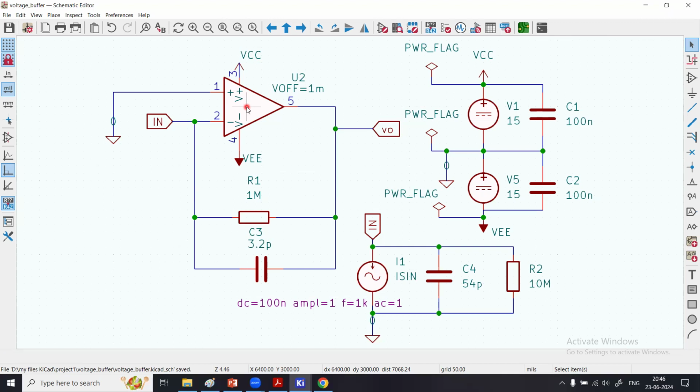Different manufacturers across the semiconductor industry will provide you those references in the Google search. They will give you a specific part of the op-amp dedicated to building a smoke detector application, in which you can configure the op-amp by the manufacturer as a transimpedance amplifier. Okay, that is perfectly suited for the photodiode application we have considered.